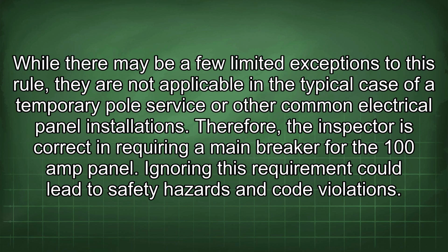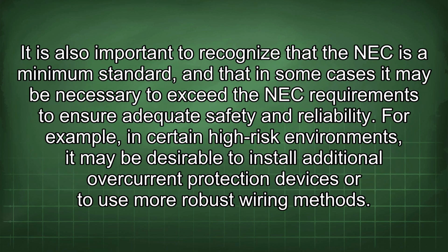Therefore, the inspector is correct in requiring a main breaker for the 100 amp panel. Ignoring this requirement could lead to safety hazards and code violations. It is also important to recognize that the NEC is a minimum standard and that in some cases it may be necessary to exceed the NEC requirements to ensure adequate safety and reliability.